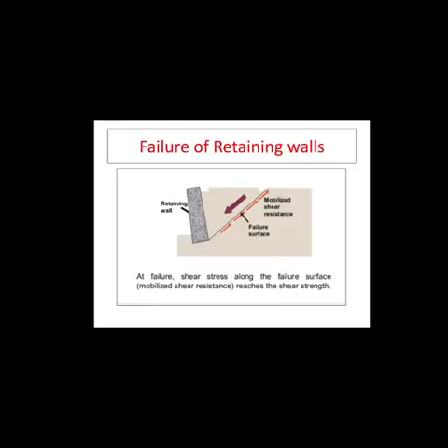The next slide shows a retaining wall retaining earth. Retaining walls are used to retain the soils, and the movement of these walls induces critical shearing zones in the retained earth behind them. The soil mass contained in an approximate wedge behind the wall slips along a failure surface, thus shearing or cutting it off from the rest of the soil mass. We need to evaluate the earth pressure acting on these retaining structures for their safe design. The evaluation of the strength of the soil helps in achieving the same.